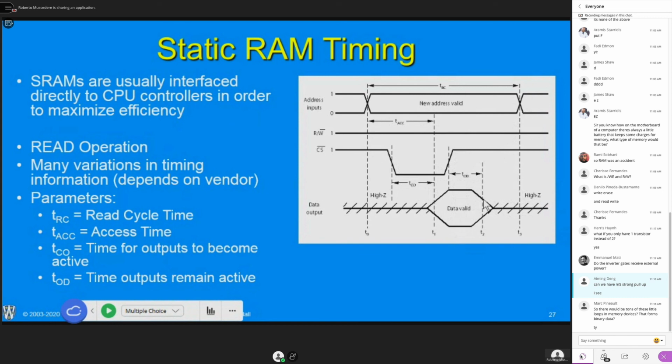Okay. So again, if I want to operate my system faster, I would need to make sure, first of all, that I'm reading my data at this particular interval of time. If I move chip select further down here before I change it, I'll obviously increase this window here. But if I can't meet the timing, I again have two options: either get a faster memory device or slow down my system.